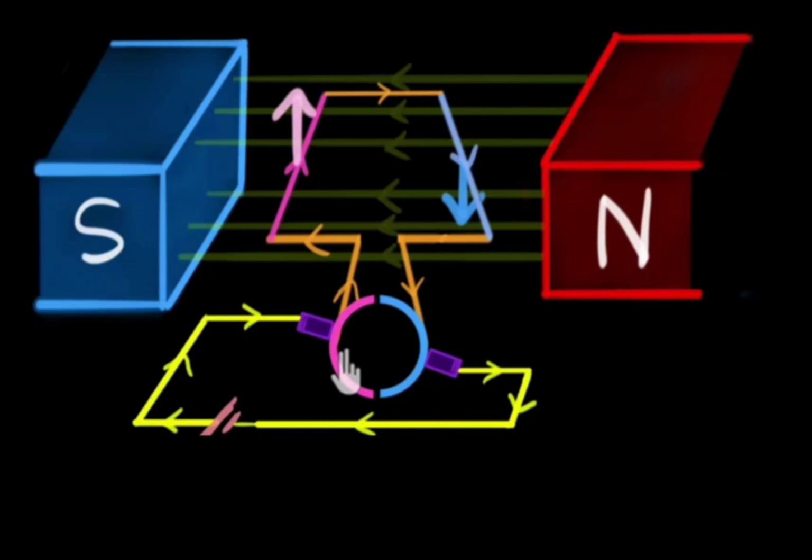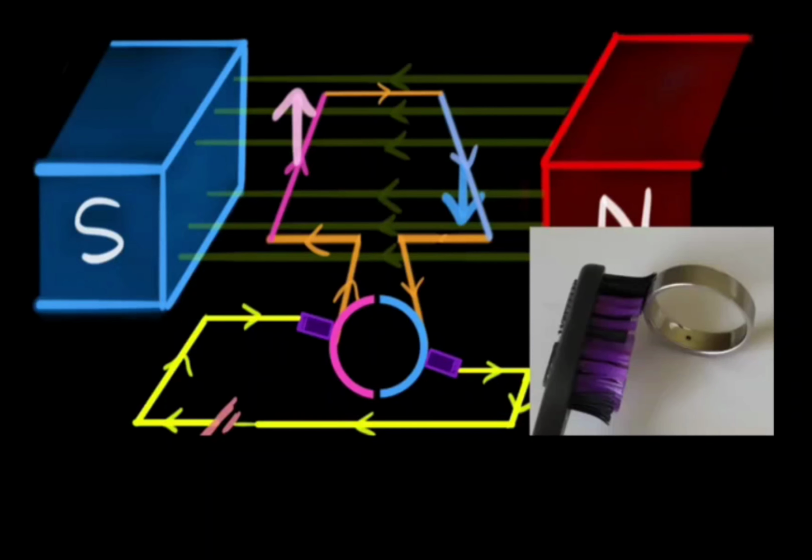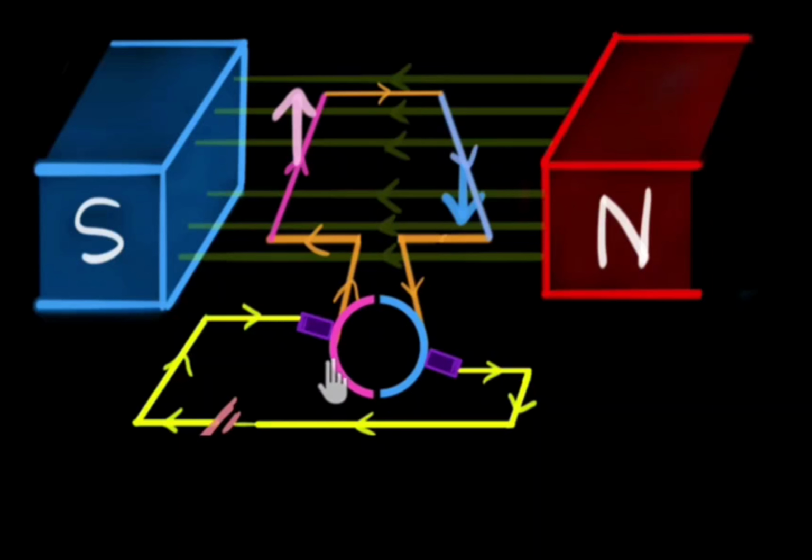In this case, when the brushes are on the neutral axis, all the armature conductors lying under the north pole carry currents in a given direction, while those lying under the south pole carry currents in the reverse direction. The commutator serves to reverse the current in each armature coil at the instant it passes through the neutral axis, and this relation is always maintained as the armature rotates.